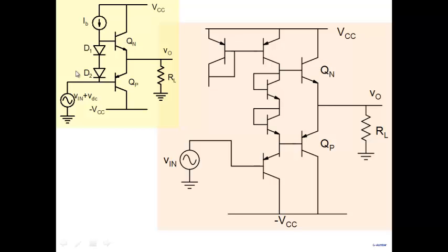So this schematic that you see here, I can realize by these two transistors connected as diodes. This is a current mirror. Any current here will be mirrored here in this part. And instead of Vin plus VDC, we applied Vin to this PNP transistor here, and we automatically get Vin plus VDC, a 0.65 here. So we arrive at this particular stage here.